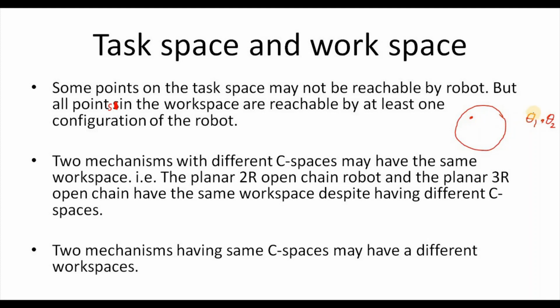So that means we can map the configuration space, for every value of the configuration space there is a corresponding point in your workspace. Okay, so this is your workspace and this is your configuration space where you have θ1 and θ2, and you call it Cspace.